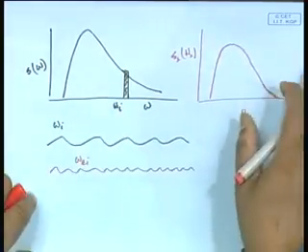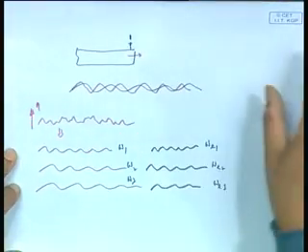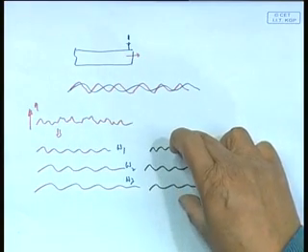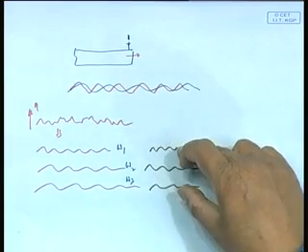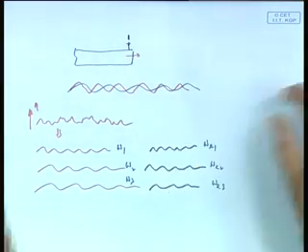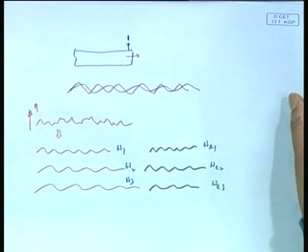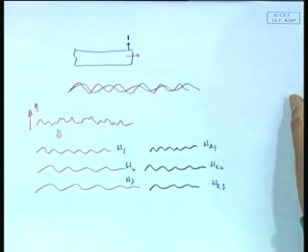In other words, the waves that I find out are measured with respect to an absolute frame of reference. You have to transform that to a frame of reference which is moving with the ship, because you are seeing the same waves as you move. So in a sense it is nothing but transferring the same waves to a moving frame of reference. And obviously if you move at different speeds, you will encounter the same wave at different frequencies. For example, if you went at the same speed as the wave, nothing is going to hit you. That we have seen, zero encounter. So I need to know this.